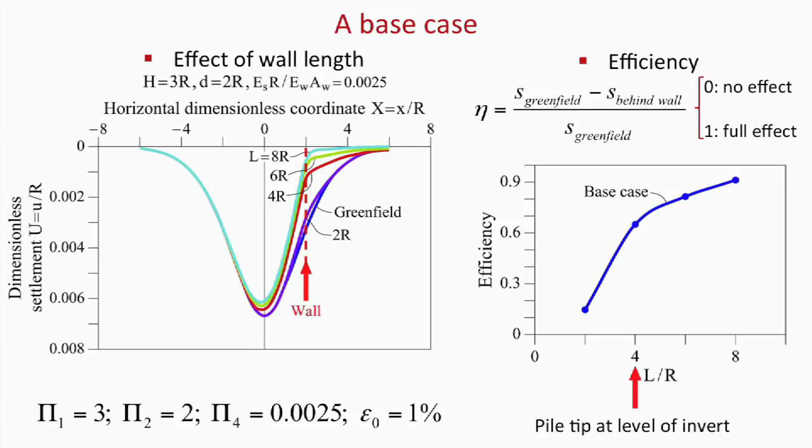So, well, you may select any point here, of course. If you are protecting the Sagrada Familia, you go deep. And this is what we did, with piles of 41 meters. These calculations were made just as an example, for a volume loss of 1%. And so here I introduce this fundamental information, 1%.